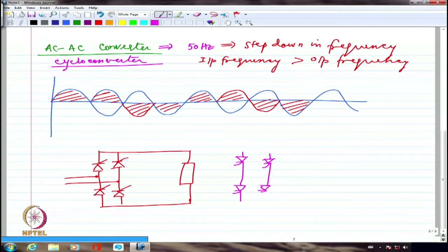So if I am having diodes, I will not be able to delay the conduction at all. So for this, if this is plus and minus, for this, actually this will be plus and this will be minus if it is diode. So I'm trying to connect the plus and minus together, right, directly, and that is definitely not done. Huge current will flow. So you cannot do this.